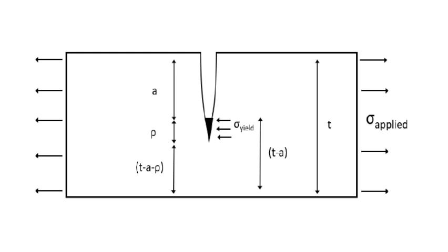And what I'm going to do is going to follow that pretty much. Some of you will also know that in the late 1960s and early 1970s, the strip yield model was used to derive the original log secant model that some of you will be familiar with. What I'm going to do a little bit differently here, though, and this is really the heart and soul of the GEM methodology, is to redo that strip yield model and redo the log secant model, but using a part through wall methodology rather than the original work that was done using through wall cracks. So it's a little bit of a twist on your mind, and hopefully you can follow things along.